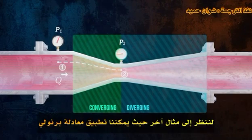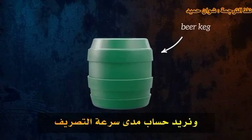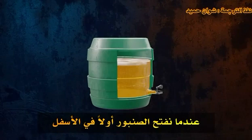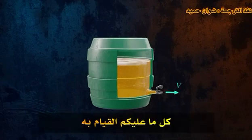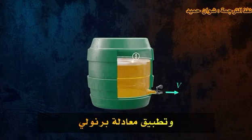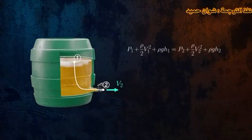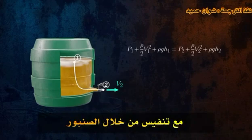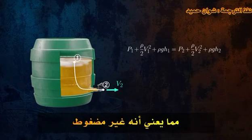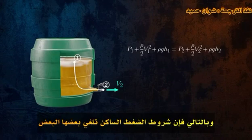Let's look at one more example where we can apply Bernoulli's equation. Say we have a beer keg, and we want to calculate how fast beer will drain when we first open the tap at the bottom. All we need to do is define our 2 points along a streamline and apply Bernoulli's equation. It's a gravity-fed keg with a vent at the top, meaning that it's not pressurized. The pressure at both points will be atmospheric, and so the static pressure terms cancel each other out.